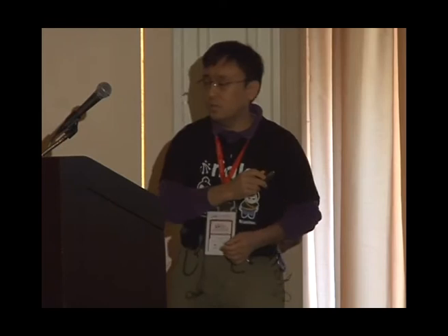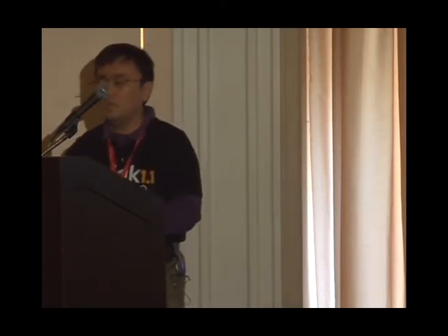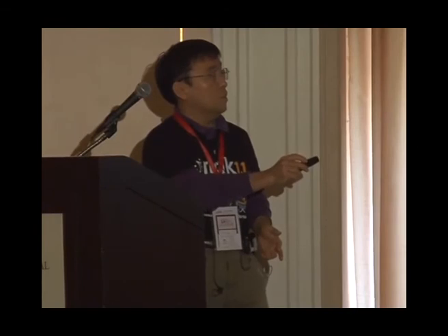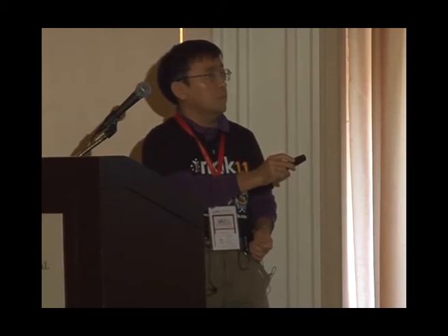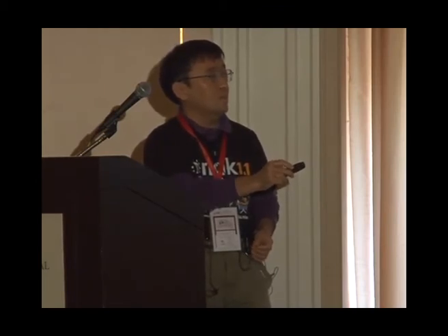And each report includes the location of the reporter and the reported station. This is the location, this is the reporter, and this is the reported station. For example, this locator is in Namibia, and it locates a station transmitting from Hawaii. You can identify this information from the prefixes of the call signs. And there's frequency information in kilohertz. It's about 140.177 kilohertz right here, including signal strength and transmission speed. This kind of information is all collected automatically 24 hours a day.